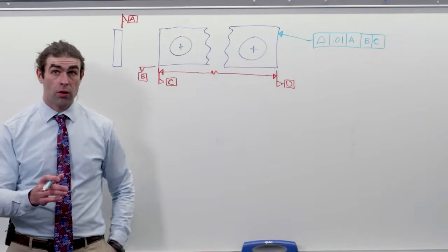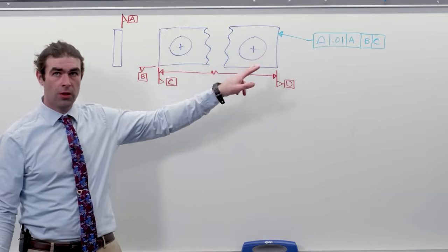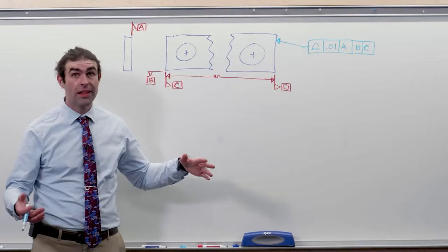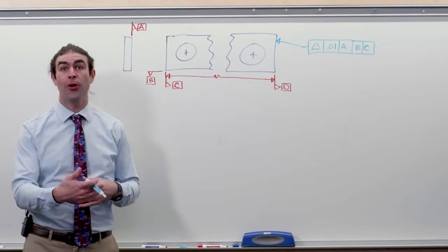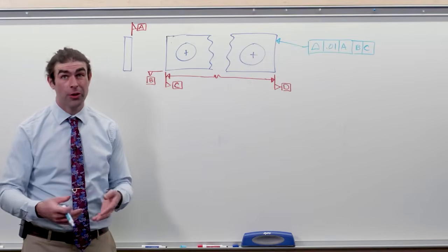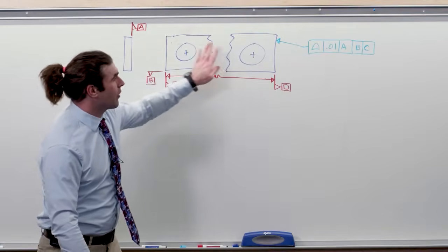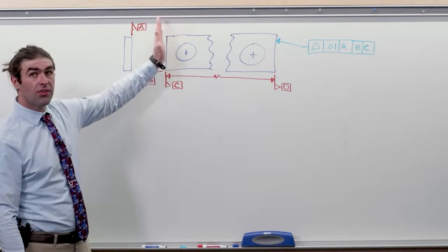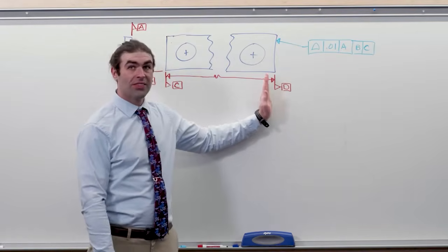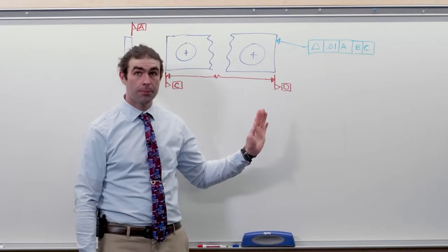So let's say we've got a really long part, right? So we got a hole on this end, hole on this end. Again, all the details on this part aren't shown. I use this as an example to talk about multiple datum reference frames. It'll work just as well for this profile discussion. Datum A is the large flat surface. Datum B is this surface here. Datum C is here. And we're going to establish a datum D on this side of the part.